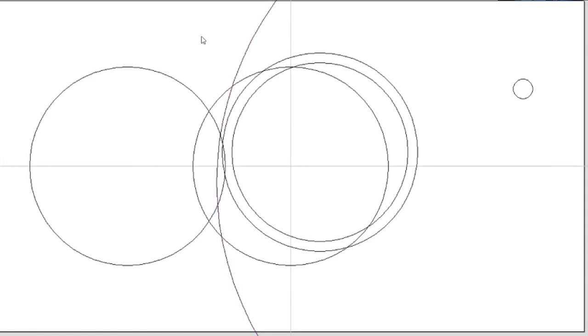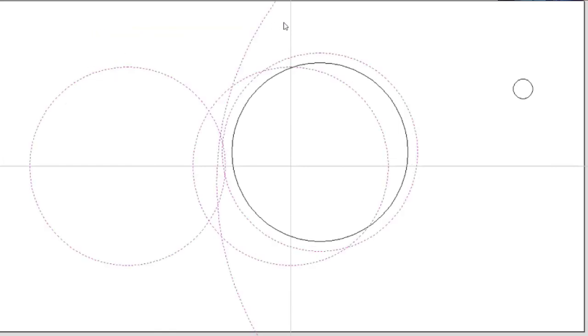Now, if I go from left to right and make roughly the same size box, and I let go, it didn't select it. Nothing. Because when you're going from right to left, it's going to select anything that box is touching. So if I just barely touch this other circle right there, now it's selected everything that box touched.